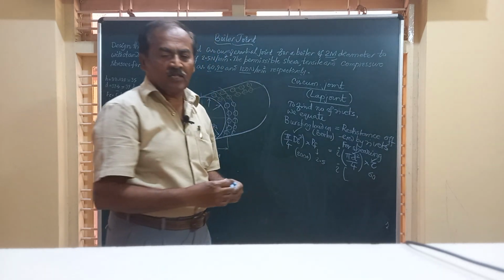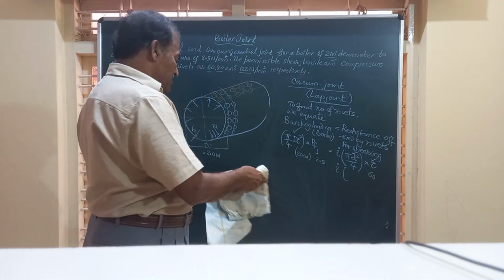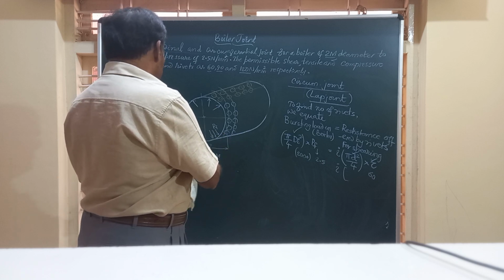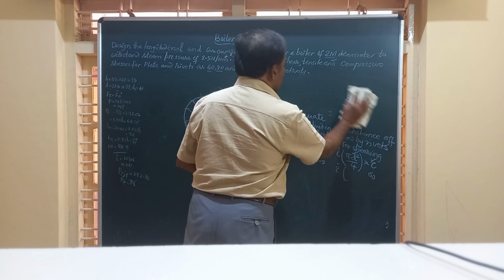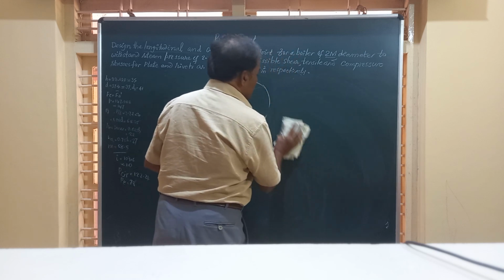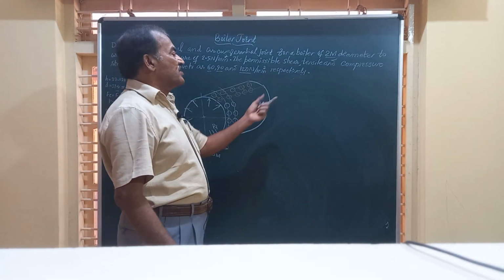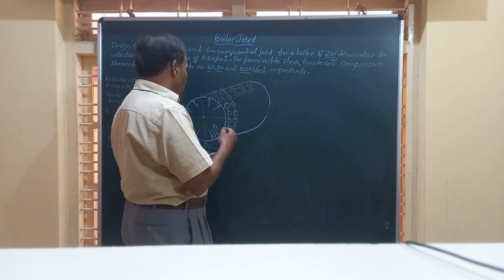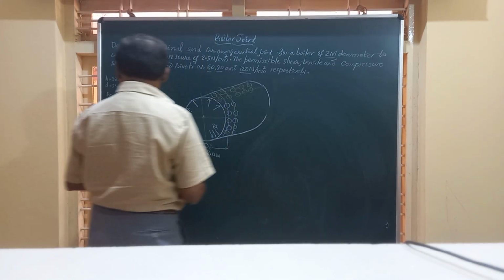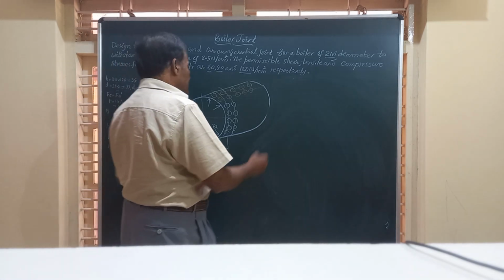So we know all the parameters in the equation, and you can find I, the total number of rivets required for the circumferential joint. And remember, the size of the rivets used for this joint is the same as that of the longitudinal joint. Friends, you get the value of this I as 108.6.